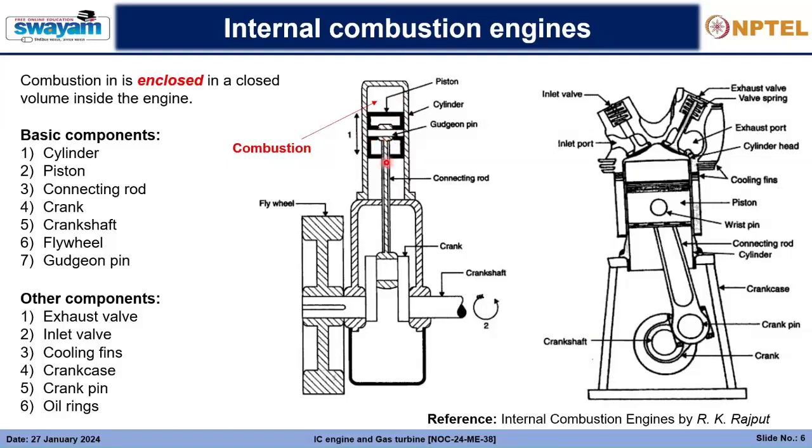And accordingly, there is an unevenness in the power in the entire cycle. So to even out these powers, the flywheel will take up a huge amount of energy when the power stroke is being performed, and accordingly it will release it in other strokes where the power is not produced. So this is the reason why a flywheel is used, and you will get to know about it later.